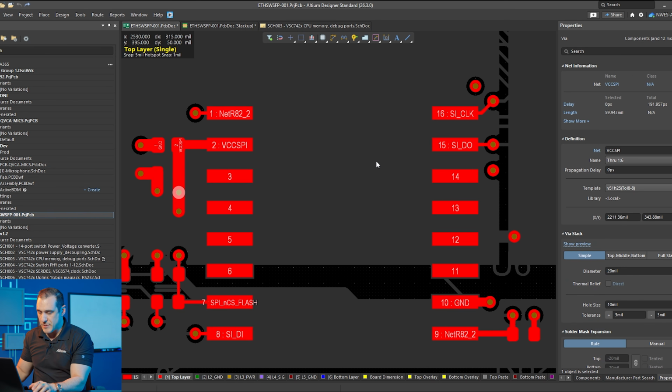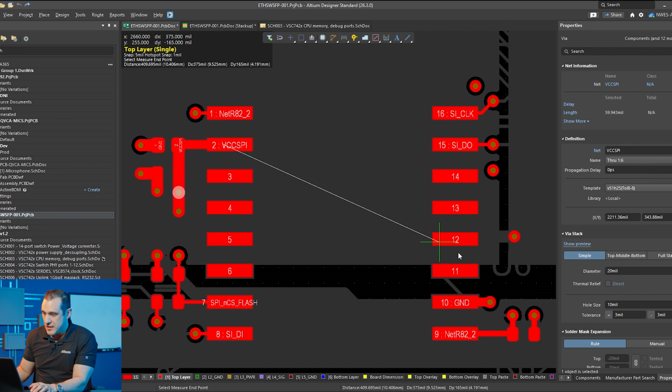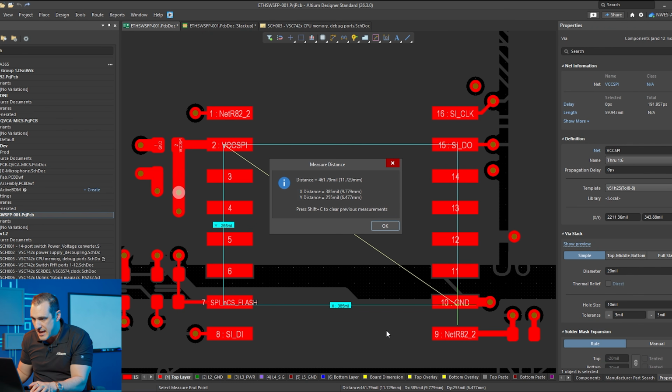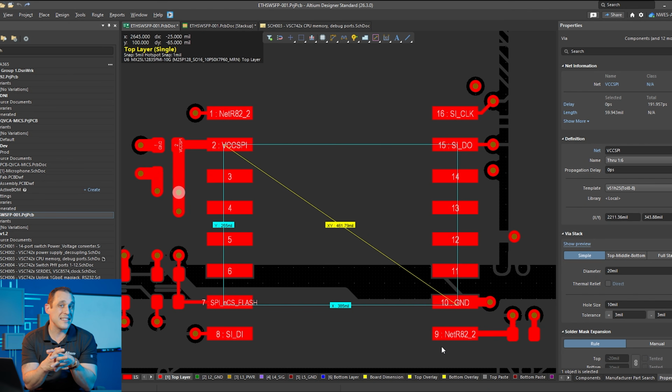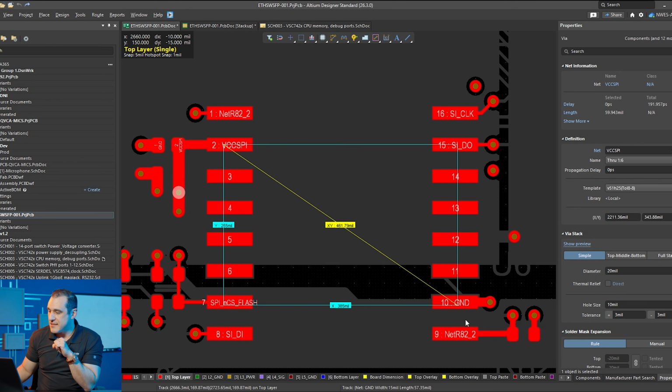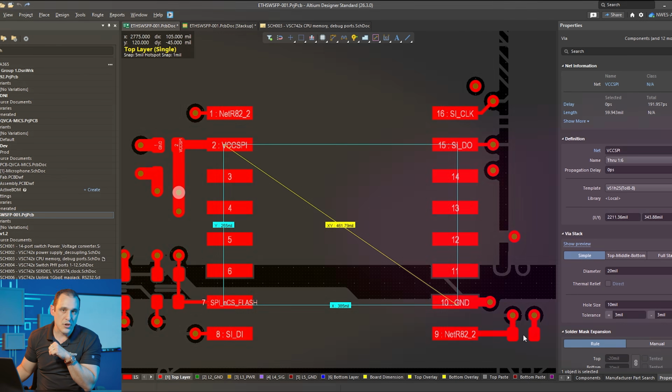Now, just a rough estimate of the distance between this power pin and this ground pin is about 1/2 inch. So this would be about a 3.9 nanohenry connection just between this capacitor and this ground pin on this integrated circuit. Well, that 3.9 nanohenries is about 4 times as large as a typical PCB via that would connect back to the ground plane.